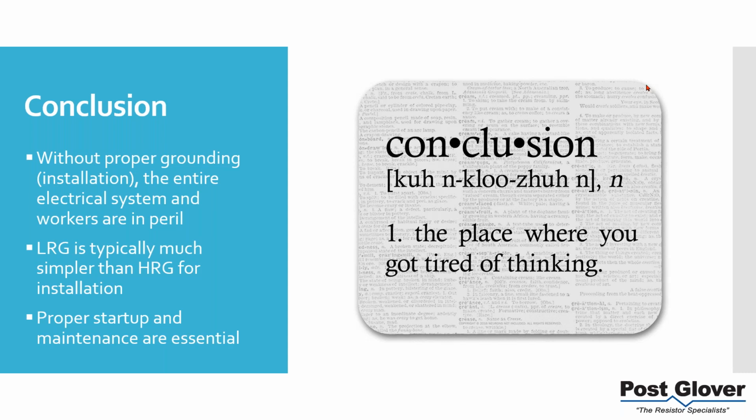Medium voltage typically has higher capacitive charge current values. Essentially, if the current flowing through your resistor is lower than the capacitive charging current, you're not going to be able to use resistance ground. In other words, if your system capacitance is too high, your charge current's too high, you cannot use resistance ground, or at least high resistance ground. So you definitely want to calculate that at medium voltage. I thought you said measure, so sorry about that, but go ahead.